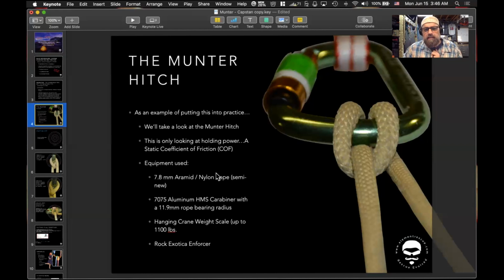We tell you this information because one of the downsides that people don't really understand with the Capstan or the belt friction equation is that if I change my rope, not even diameter, just the manufacturer or the materials it's manufactured out of, it will change my answer. It'll change what those angles are if it's a stiff rope versus a very soft rope. There's so many different factors. It doesn't account for the nonlinear behavior of ropes or the bending rigidity, but it gets us in that ballpark and it allows us to understand how we can work things out dynamically when we don't have time to think about everything and we don't have a lot of equipment.